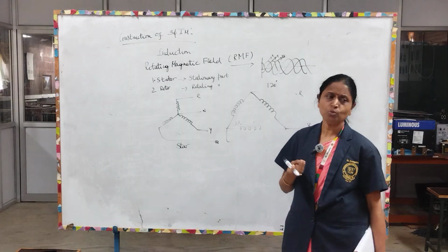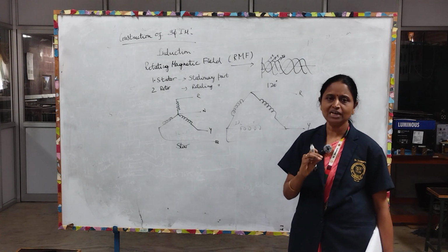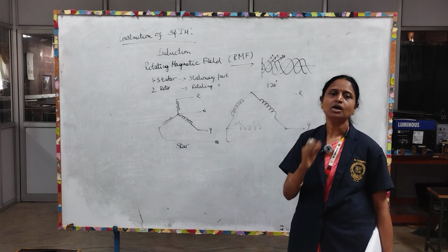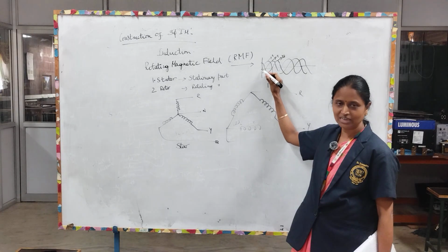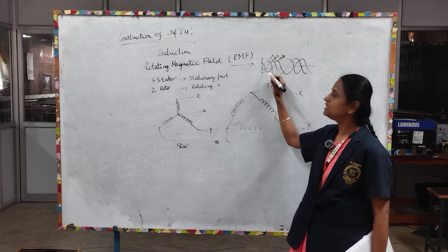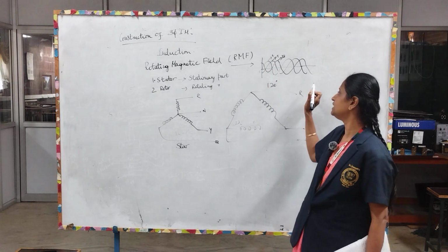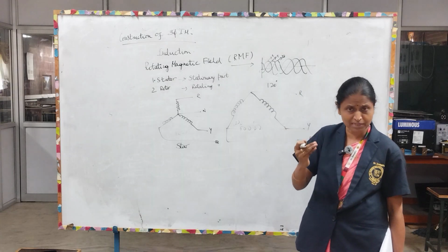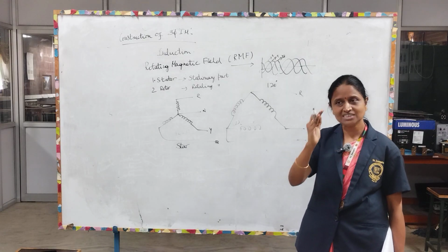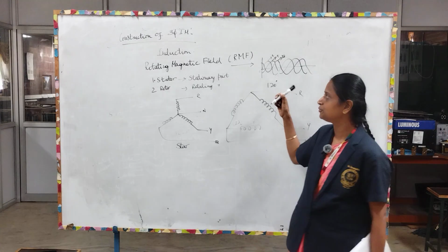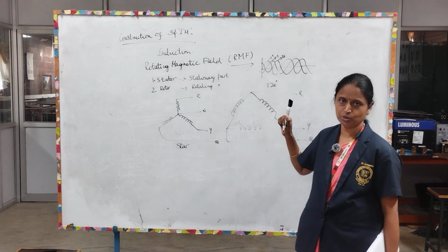And I have already told you, the induction motor works on the principle of the rotating magnetic field. It is nothing but the field or flux having constant magnitude, with its axis continuously rotating in space. If I take R as reference, it starts from the origin, Y is shifted from R by 120 degrees and B is shifted from R by 240 degrees. So you have a phase displacement, but the magnitude won't change. Only at each and every instant the phase or angle will be changing. That is the main thing we have to consider. That is the basic working principle behind the induction motor.